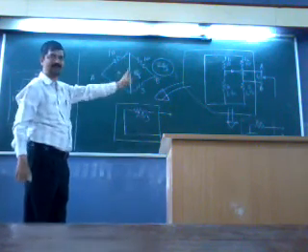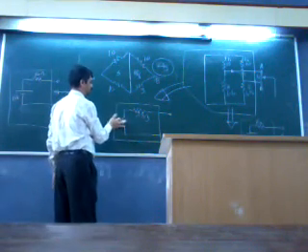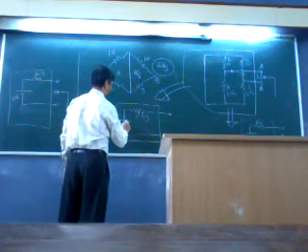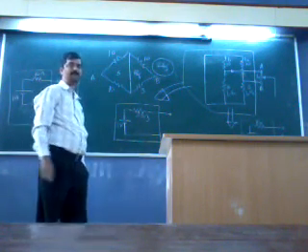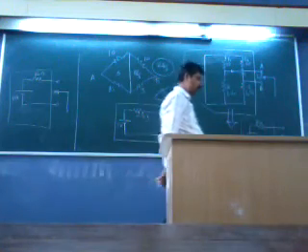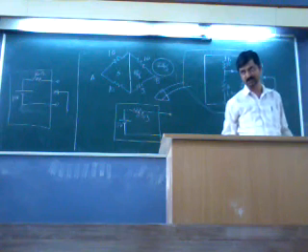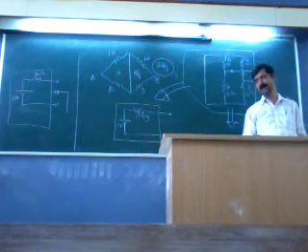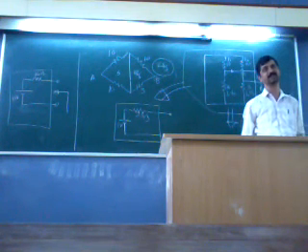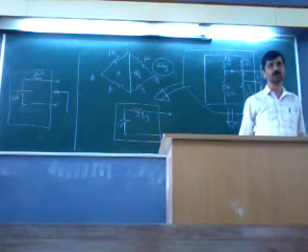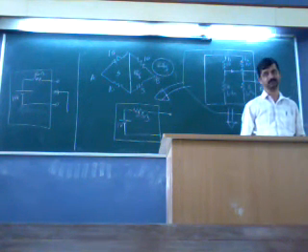And I have not actually made the voltage source 0. So whatever VTH I found earlier happens to be here. So I find VTH by open circuit voltage, and I find RTH to be the effective resistance between the terminals by shorting the voltage sources.